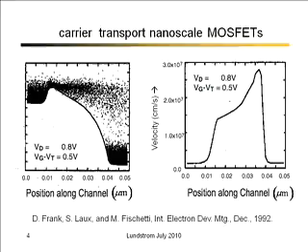So it's a simulation that treats electrons as particles. What you're seeing on the left is the conduction band versus position for a hypothetical, I think this was an SOI double gate transistor with a 30 nanometer channel length. Each dot represents an electron that's being tracked through the transistor from the source to the drain by the computer. As it is accelerated by the electric field, it undergoes random scattering processes.